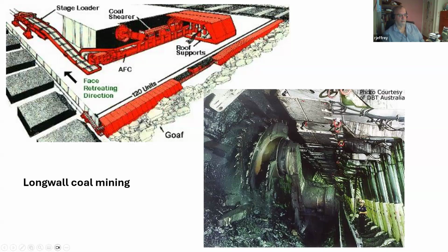And that presents two problems. One is when it finally comes in, it may come in very quickly and displace any gases that are in that void, creating high velocity wind blast risks in the mine workings, with wind velocities recorded of several hundred kilometers per hour. And also those gases tend to contain methane and CO2, which can result in displacement of explosive or suffocating gases into the mine workings. So that's obviously to be avoided.